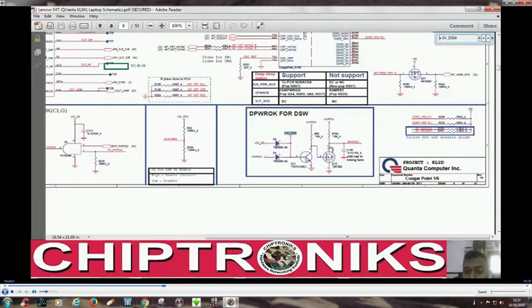As we know, in an N-channel MOSFET, to turn on this MOSFET, the voltage at the gate should be higher than the voltage at the source. VGS should be higher. But here you can see the source is connected to the ground and the voltage at the gate is also 0. So this MOSFET is turned off.